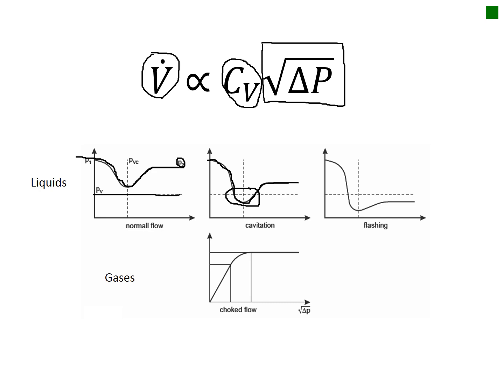If our downstream pressure P2 is low enough, we will come in at P1, go through to where we're below the vapor pressure of that liquid and remain below. And this is what's called flashing because it just flashes into a vapor. Both of these situations will limit the flow rate of that liquid flowing through the valve.